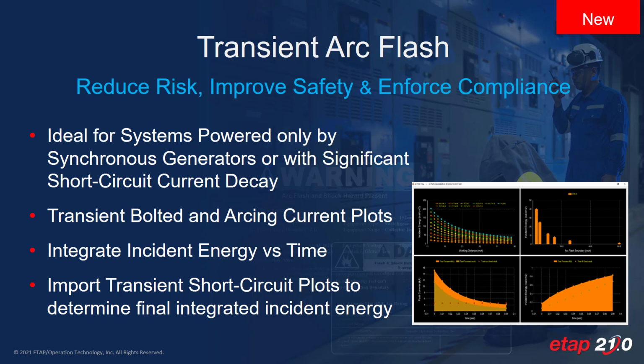We are aware that the IEEE 1584-2018 method does not contain a clear way to specify the limits of system X/R. This tool can be used to account for this effect for systems with unusually high X/R ratios. Furthermore, the generator could decay quite quickly for some generator excitation systems, such as static excitation systems. This solution allows the engineer to model such decay and consider its effect in the overall integration of the final incident energy.